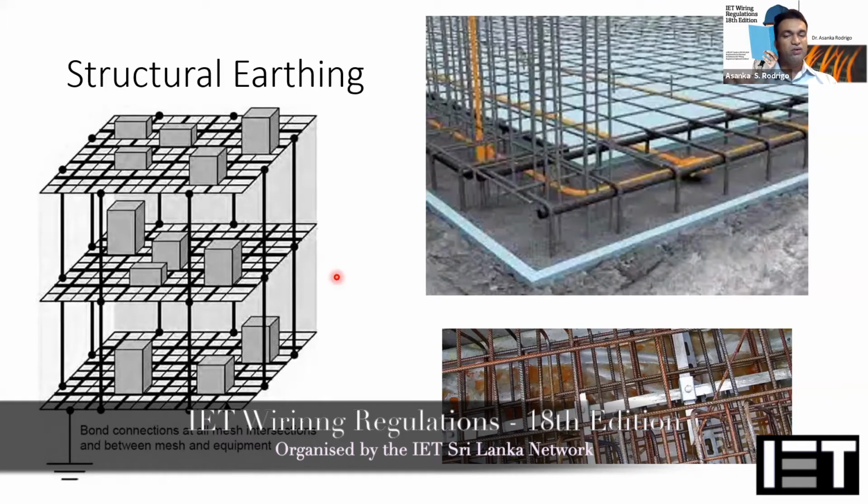But the general rule is overcurrent protection is mandatory at every origin. RCD protection, or residual current protection, is mandatory for the installation, but it's up to the designer to decide at what level of the distribution board they use the RCD protection.